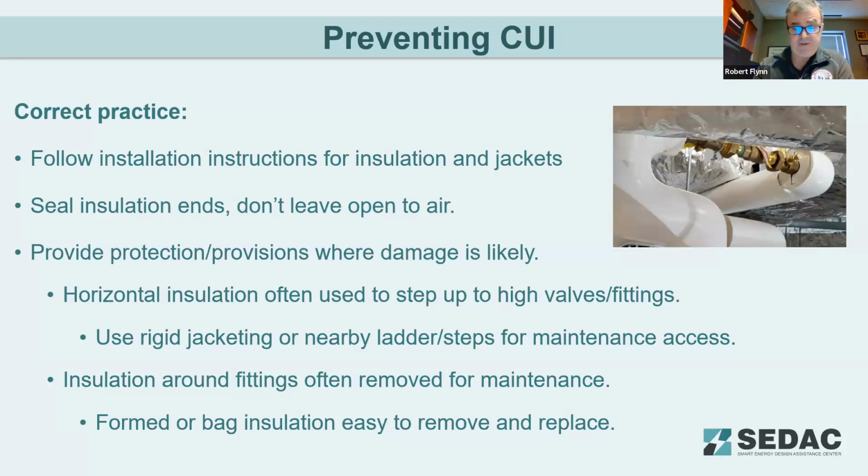So that's one of the things we do when it comes to preventing damage to insulation, as we'll be seeing going forward. Some of the correct practices: follow installation instructions for insulation jackets, seal insulation on the ends, don't leave them open to the air, and provide protection where damage is likely.